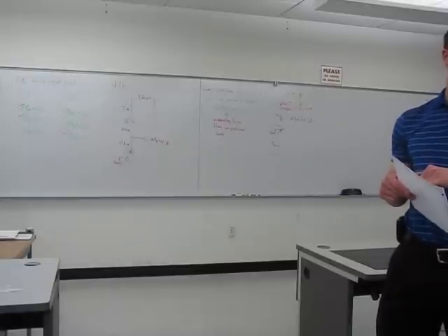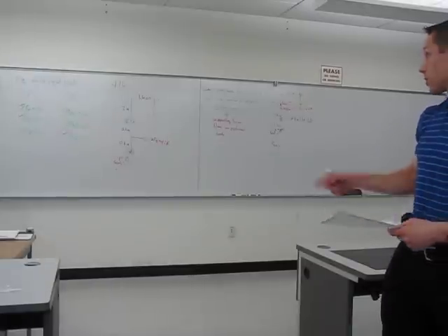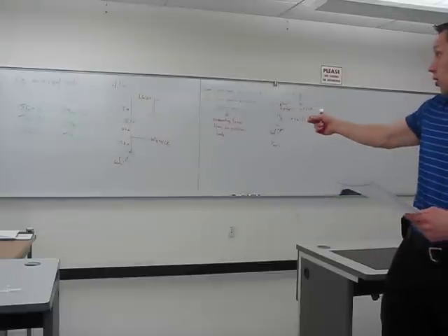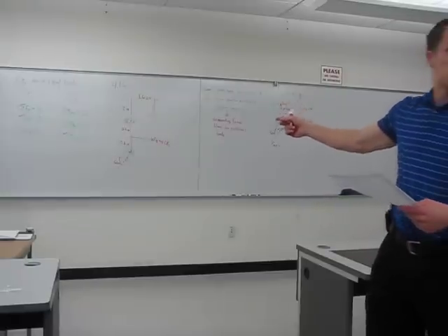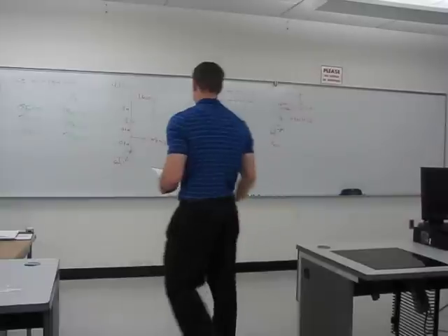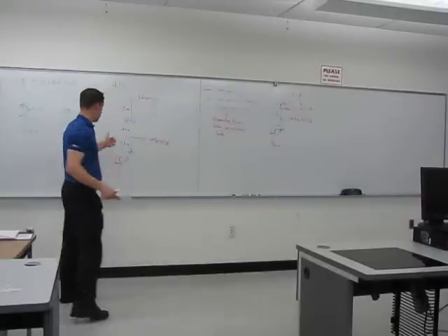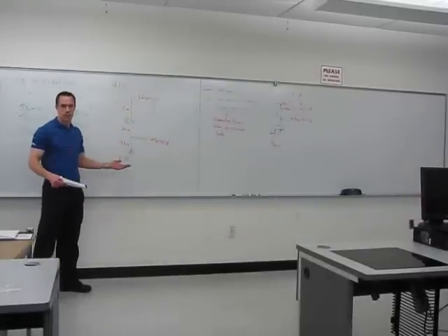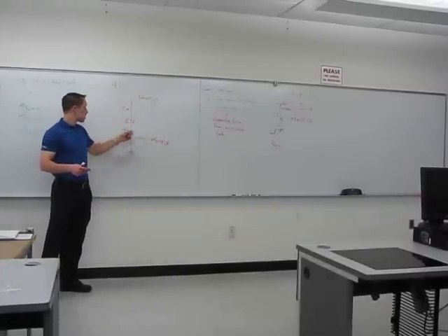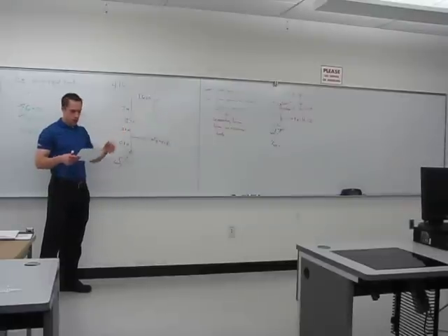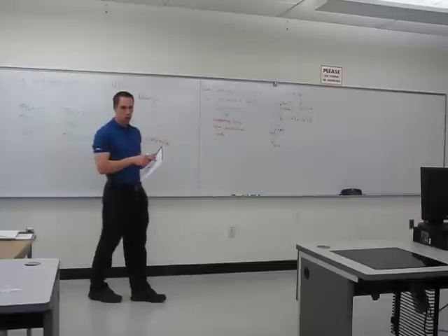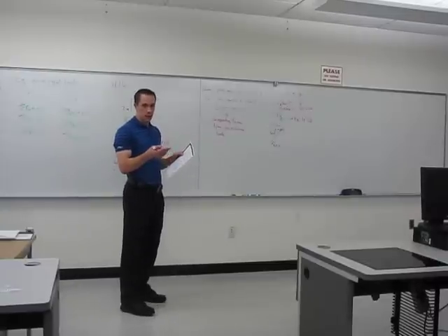So, rollers, wheels, anything that's like a wheel, or has a rounded surface: the reaction force is just perpendicular to the tangent line for the surfaces that are in contact. Okay? Pins, we see those a lot. They have an X and a Y component. The short cable that you see there, that's just a rope. We already know how to handle ropes. They can only pull in the direction of the rope.